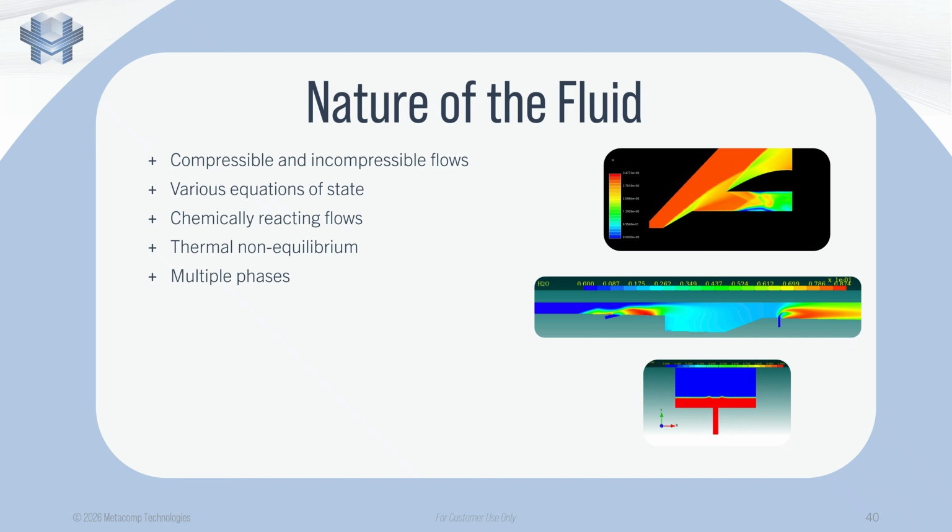Fluid flow may involve chemical reactions, such as combustion in engines or processes in reactors, adding further complexity to simulations. At high temperatures, thermal non-equilibrium effects must be considered. Many engineering applications involve multiphase flows and phase change phenomena like condensation, evaporation, or solidification, requiring special models for interface dynamics and heat transfer. The ability to efficiently model chemically reacting flows plays a crucial role in CFD by enabling the accurate simulation of processes where chemical reactions and fluid motion interact.